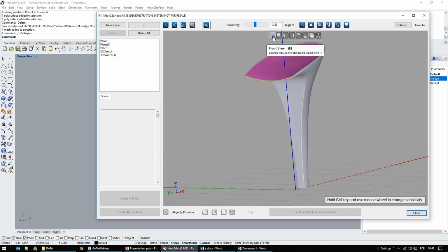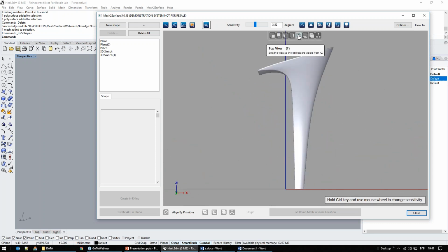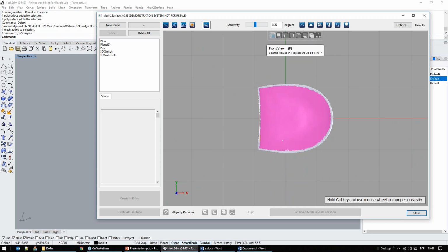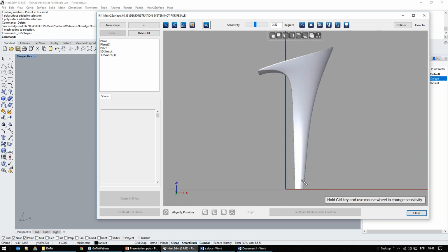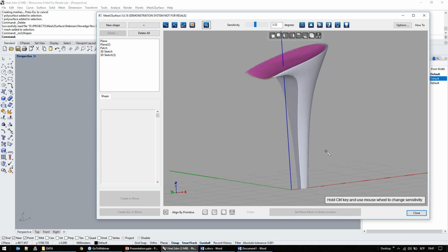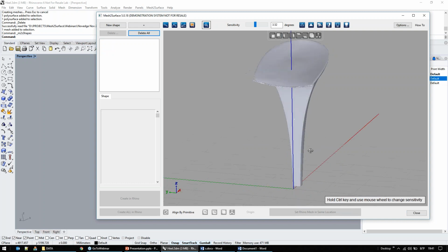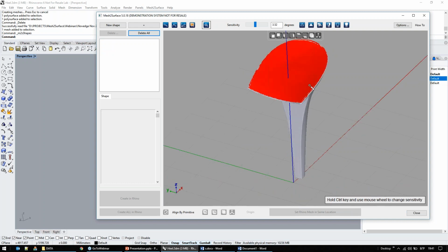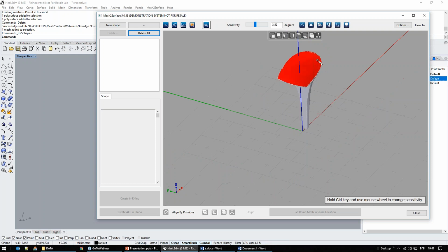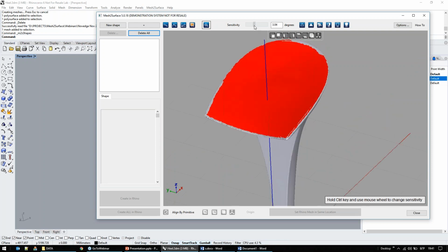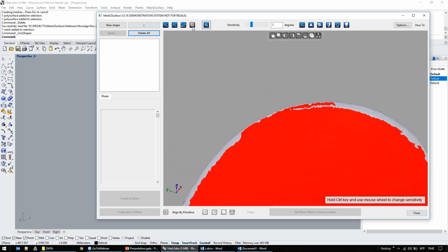I mean, it's vertical, which is okay. If I look at it from the top, the axis is not in the center, but in my case, it doesn't matter. Then I have several shapes here, which I will delete and create from scratch. So I will choose my top surface and reduce the selection a bit so it doesn't influence my shape. I will remove some of them here.